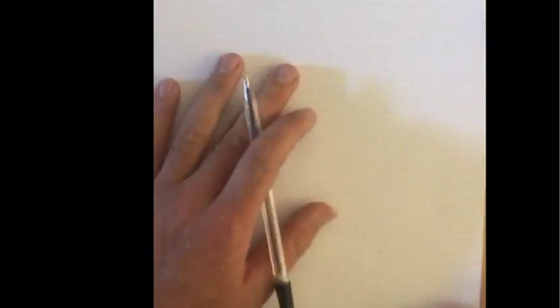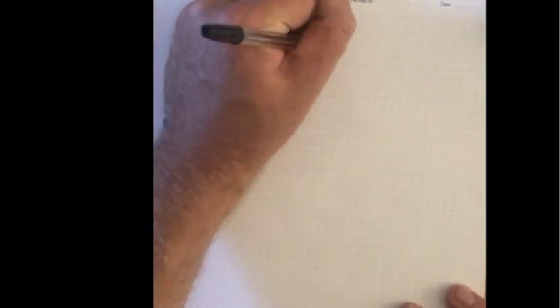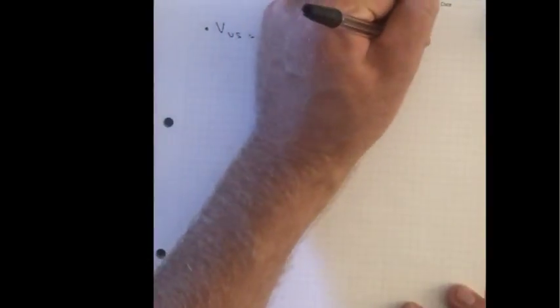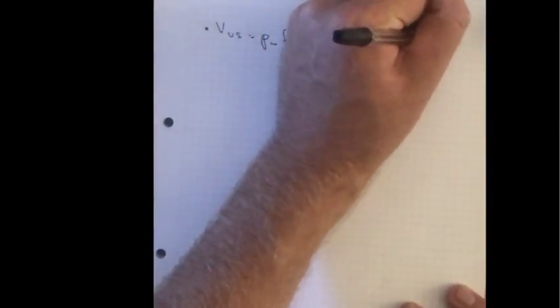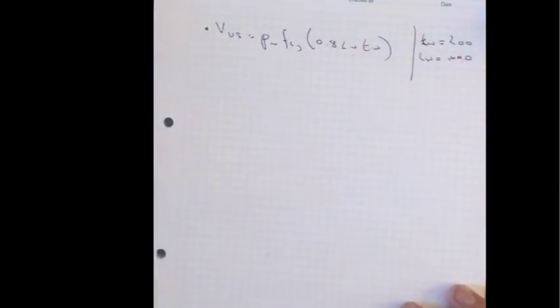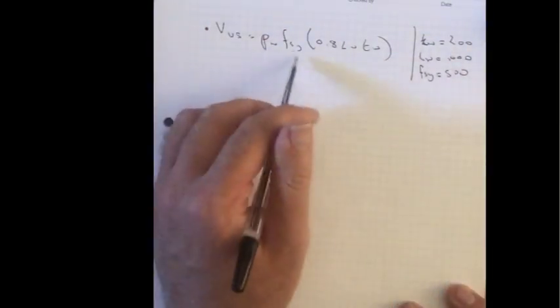Next, we have the shear strength contribution from the wall reinforcement. So that's 11.6.4, Vus equals reinforcement ratio times, as we said before, thickness of the wall 200, length of the wall 1000, and yield strength of steel, 500 MPa.